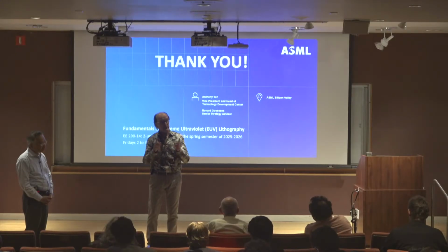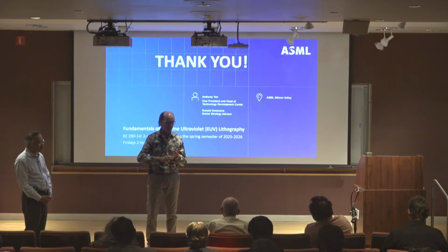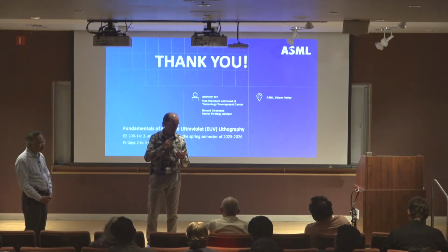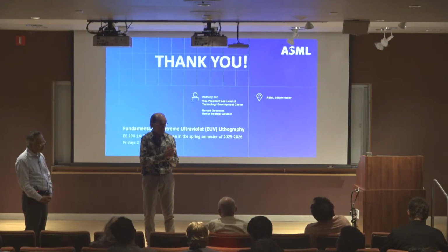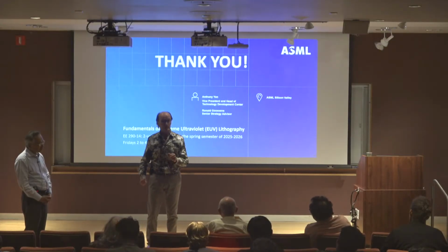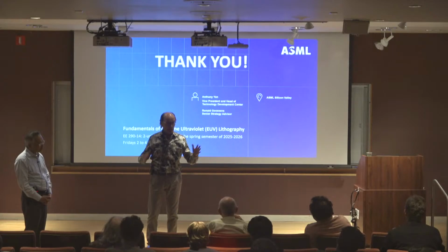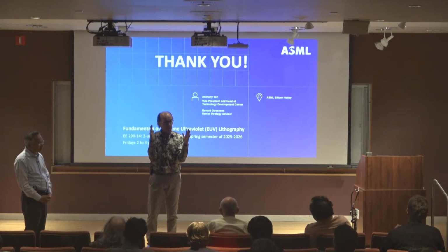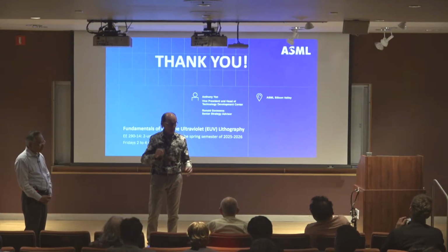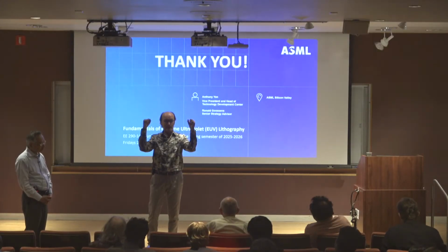But for every layer, metal 0, metal 1, metal 2, contact holes, vias, every layer has its own illumination. And let me take your example a little bit to an extreme. If I want the absolute smallest pitch in one direction, I would use a dipole with only 2 tiny little pieces of light here.